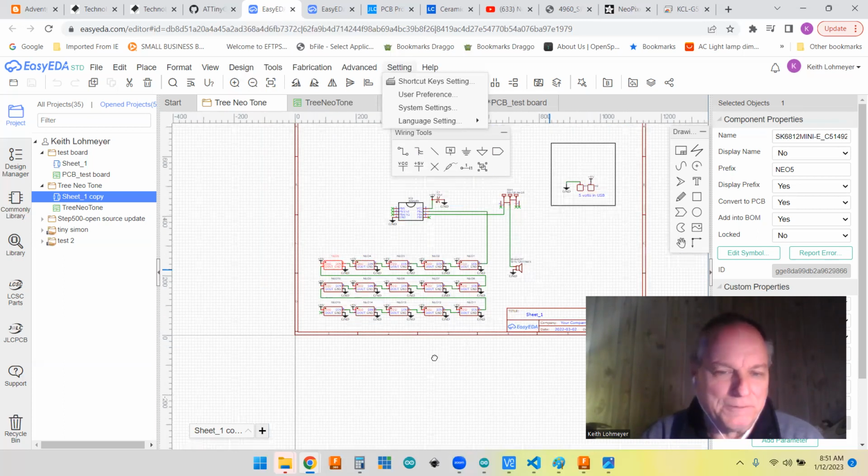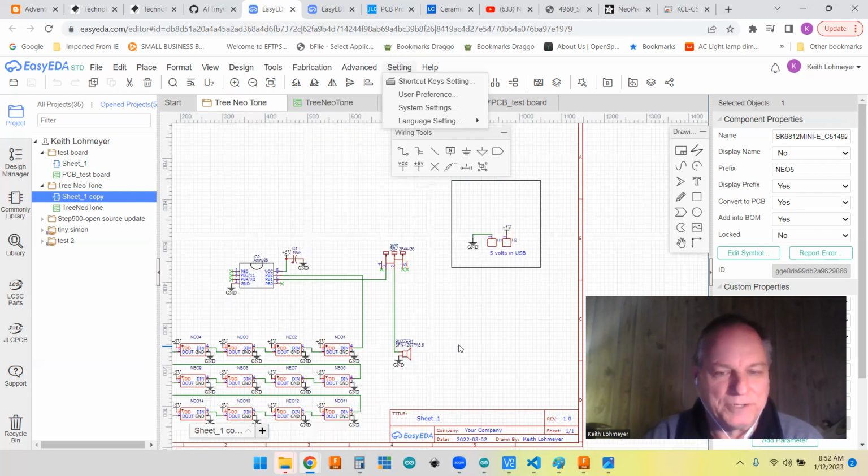So once you get your schematic drawn up and everything, by the way, the ground and 5 volts are called nets. So they don't actually connect to each other with these wires, but anytime you have one, this is connected to this and connected to ground. Same way with the 5 volts. You can also have your own nets. Like if you have an Arduino pin and you don't really have room to run a wire all the way through, you can have a net with a pin, or name it whatever you want.